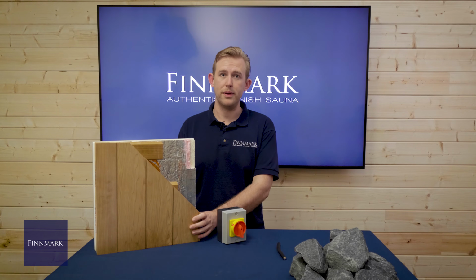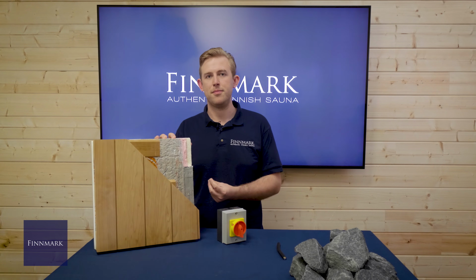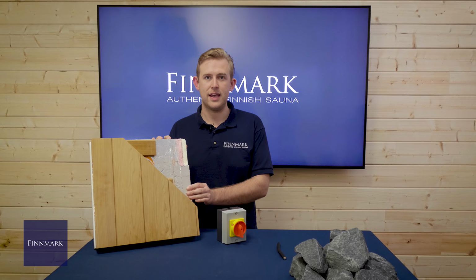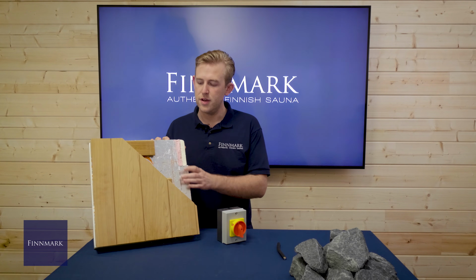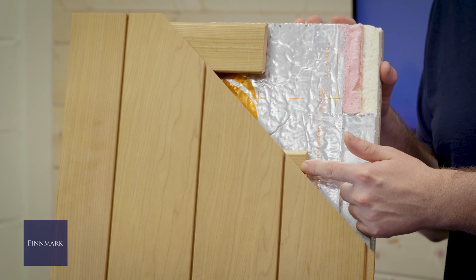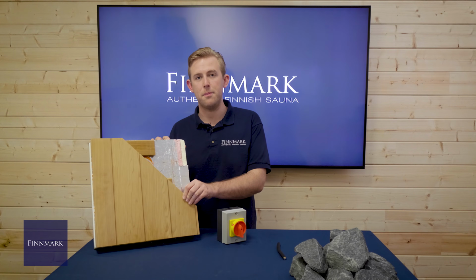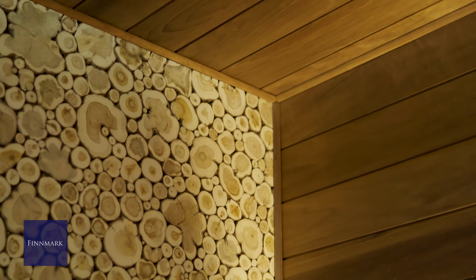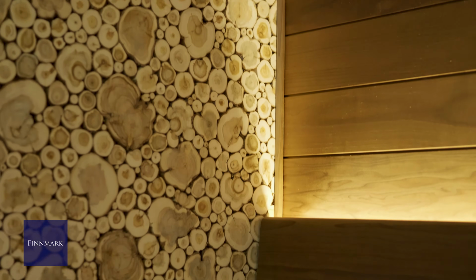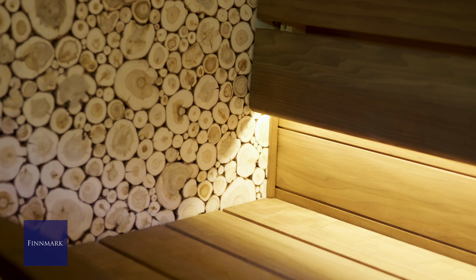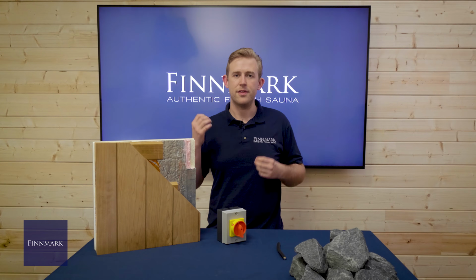The thickness of the wall build-up is typically 12.5mm of fireboard where required, 30mm of Kingspan Sauna Satu insulation, 20 to 25mm of thermo-treated batten, and 15mm thick cladding in the case of European cladding species, or 17mm thick cladding in the case of American species. In some cases, there are smaller cladding options available. However, the Finnish building regulations specify 14mm or thicker.